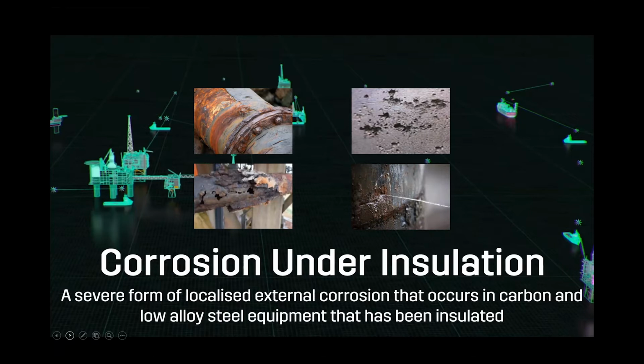It is a bit of a Swiss cheese effect with CUI. You do need to have a number of factors for it to occur, and it usually occurs when moisture enters the insulation system through the weak points such as failed seals, joints, and just damage to the general insulation system itself, or an improper insulation process in the first place. So the insulation that's designed to prevent moisture ingress actually then allows moisture to be trapped in the system, which is one of the reasons why we now see CUI being prevalent within the industry.